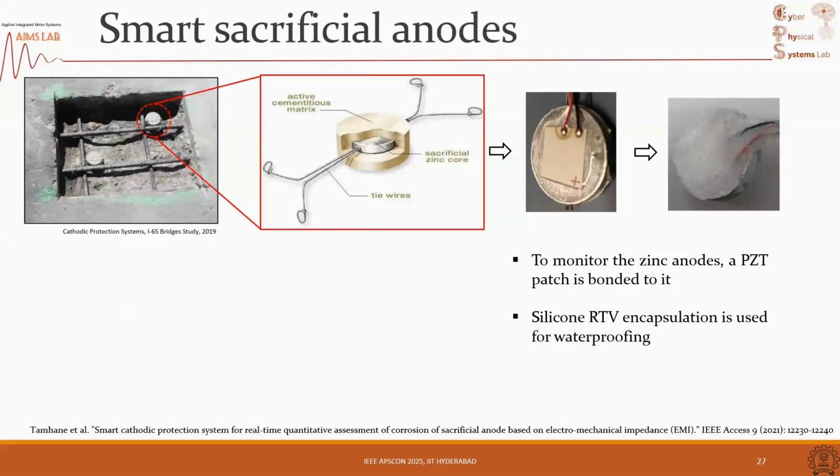So what is this sacrificial anode? Like I said, corrosion is an electrochemical reaction. So steel will rust over time and form oxide, right, which is the more stable form as the structure ages. So if I want to protect my steel from rusting, I can insert another material which is more electrochemically active, so that may rust instead. That is zinc. Zinc is more electrochemically active than steel.